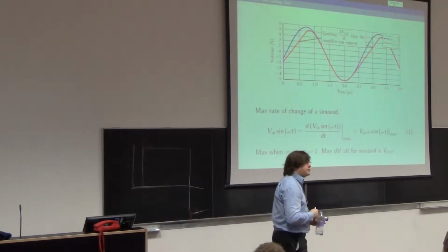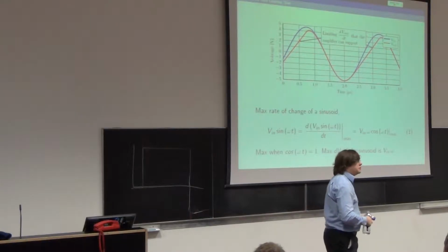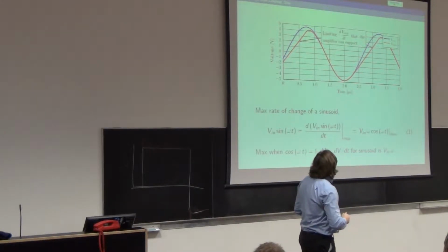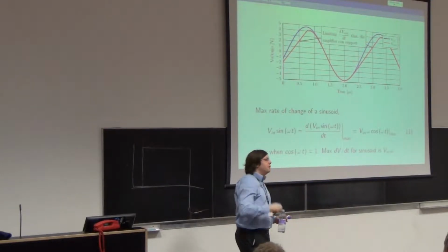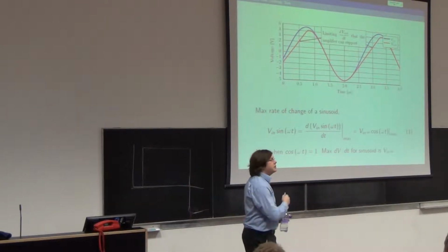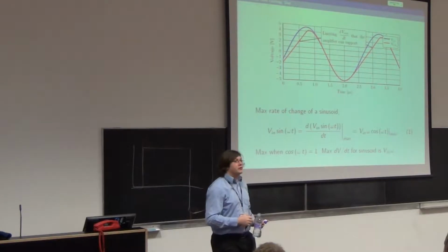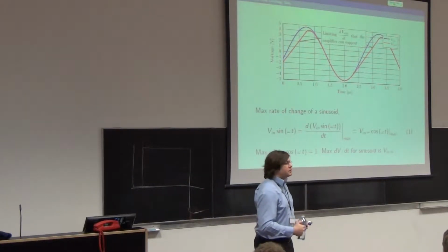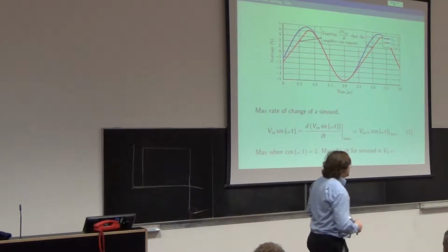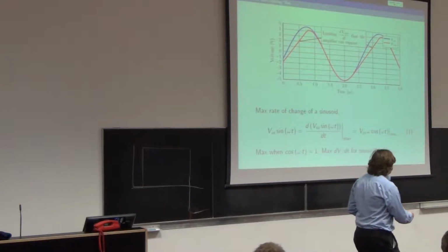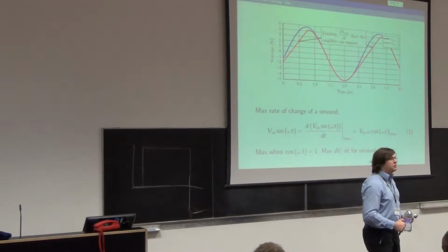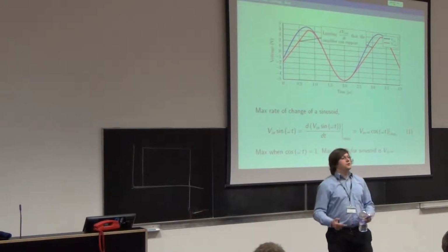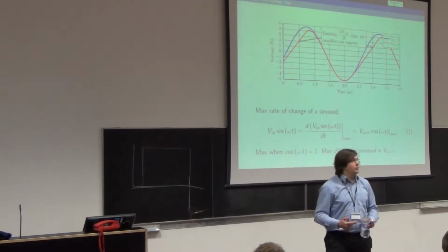If you were making some laboratory amplifier for something, or a guitar amp or whatever, and you were driving it at a very high frequency with a big input voltage, this is the sort of thing that you would observe. Alternatively, if you made an amplifier and you didn't attend to the amount of current that had to charge this compensation capacitor properly, you might find you've got slewing distortion at a kilohertz. Of course, if you want to drive a 50 Hz machine, no problem at all.